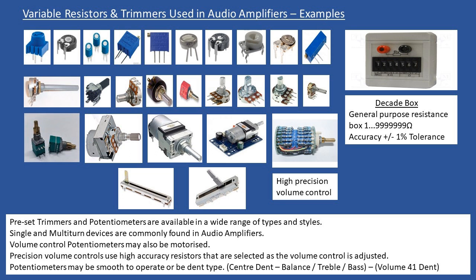But if you're working on older equipment and you have a potentiometer that fails, some of these potentiometers are generic. So they are standard potentiometers available from companies like Alps or Bourns, and you can order them with no issue there. But a lot of these potentiometers, and I'll refer back to this in the video, can be specific to an audio manufacturer's design.